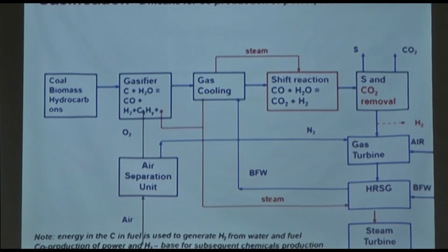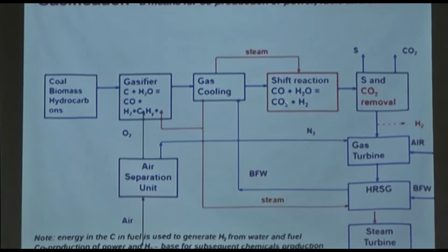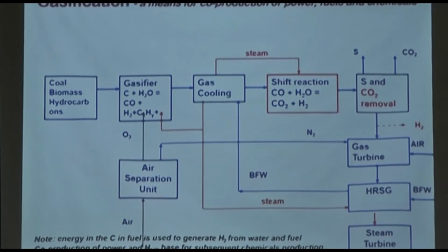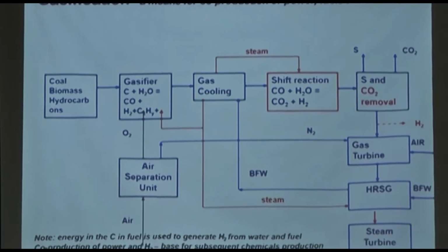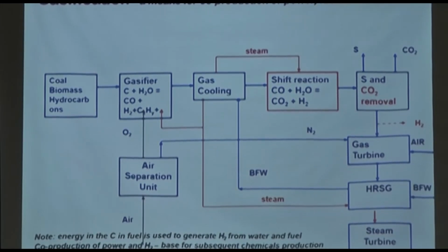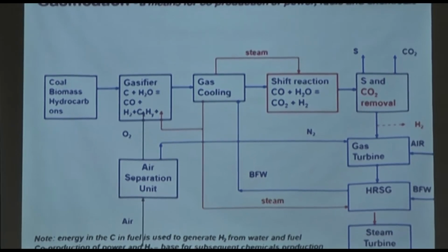That is why it is called a shift reactor, essentially giving you more hydrogen, if receiving more hydrogen is the important objective. But in order to do the shift reaction, you need to cool the gas, and we will discuss later why and how much, as there is a compromise between those two.